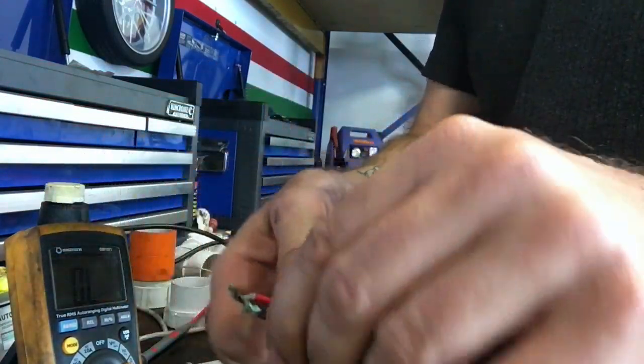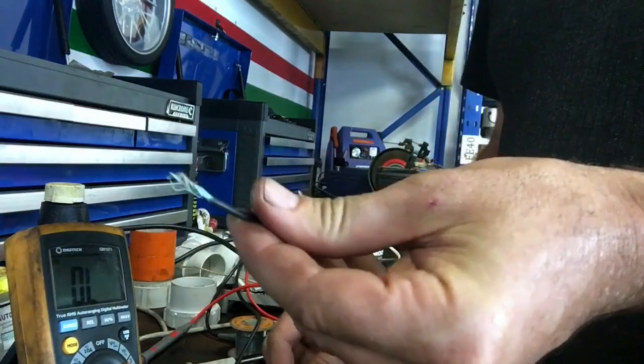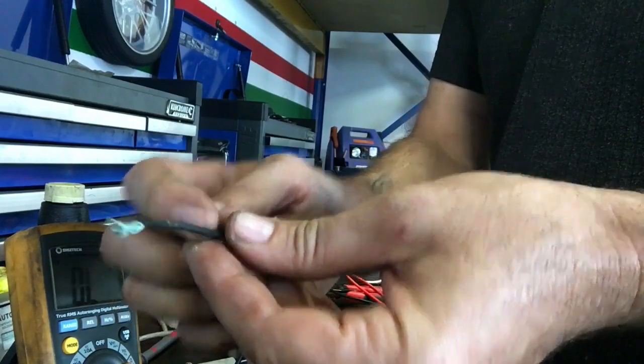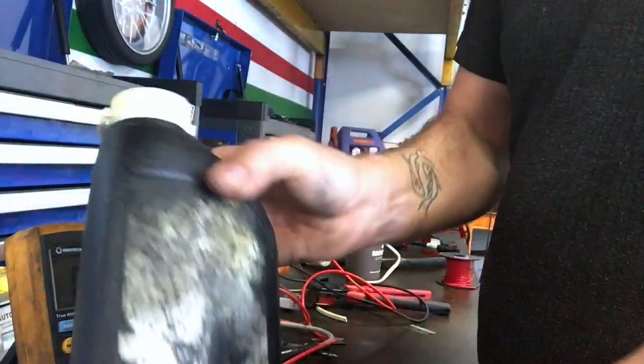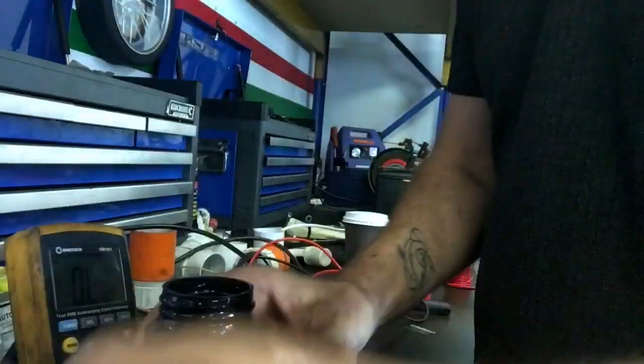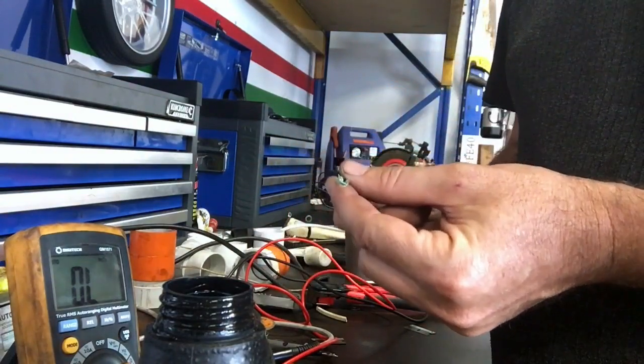Now in this case, you could cut this wire back. You can even see that green stuff coming off. Sometimes the corrosion actually travels along the casing a fair bit. So another thing you can do, this I've had forever and a day, it's actually even leaking, which is bad, is an old tub of hydrochloric acid. Be careful when you open it, these fumes are really nasty to breathe.